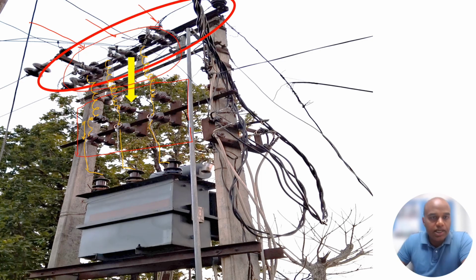The reason we use a comparatively thin wire over here is because it provides the same kind of phenomenon which is used in a fuse. So if we have any kind of fault, and let's say the current increases due to the fault, the wire connected over here melts down because of the I square R heating, and then the circuit gets opened from here. The same thing is provided in a fuse. So a similar phenomenon is provided over here for protection purposes.